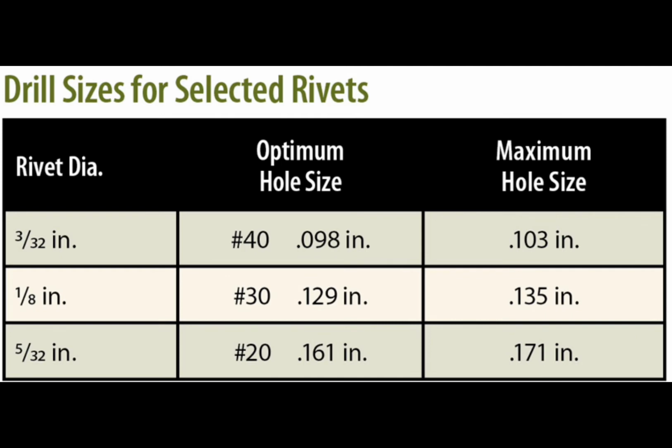What is a Barcol hardness tester? Punches a spike into composites to determine if resins have been cured. What is done to honeycomb before repairing? Remove damaged honeycomb, either replace with potted compound, or use a honeycomb replacement plug. Biggest thing: remove damaged honeycomb.